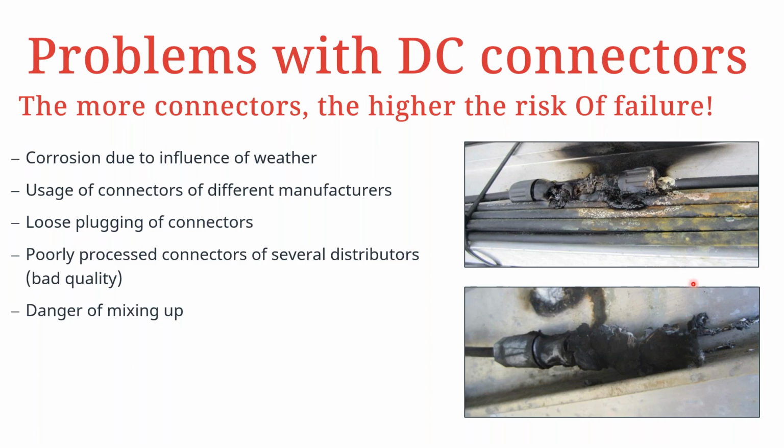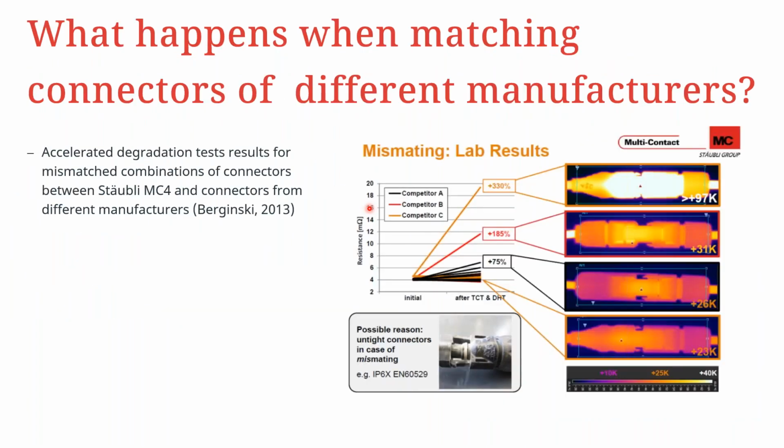So there is also availability of different studies in the market, depending on the causes of fires by the MC4 plugs, and especially when MC4 plugs from different manufacturers are used. So you can see that in this particular lab test, there is a study involving one particular MC4 plug, the Stäubli MC4, that was mixed up with other manufacturers. This was done around 2013, but the study results are still relevant to date.